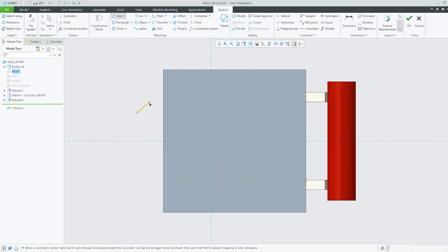Again, I can always turn that off, but as we see when we start getting into multi-body descriptions, a lot of times you're going to want to reference some other edges or some other sketches to create some new bodies. And this ability to snap to things behind geometry is actually kind of important. So you want to kind of keep that on.